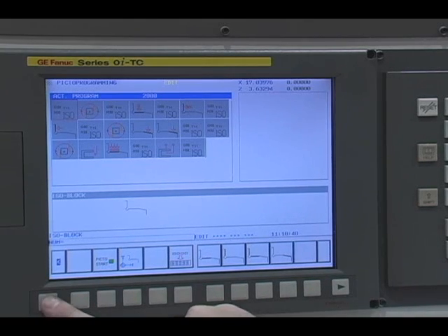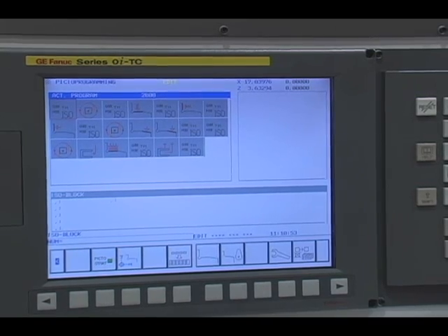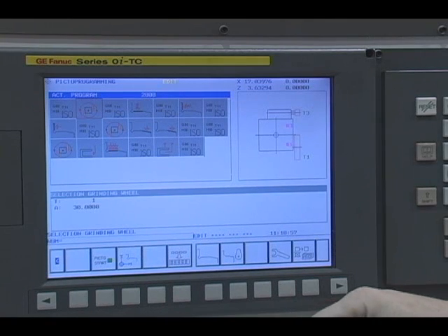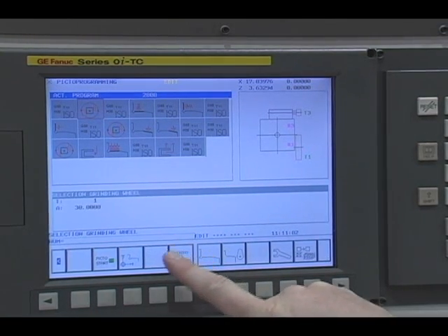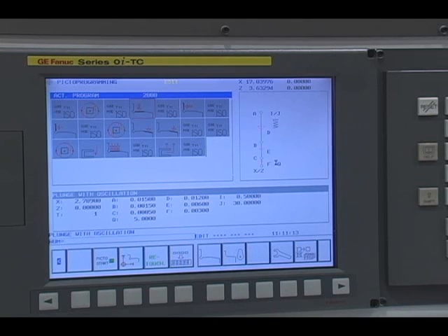So as far as our part print, or the part that we just selected, as I cursor through here, you can see on the information block the information that's in the pictogram. So my wheel selection, first operation, the grinding wheel was set up at 30 degrees. I give a command for the gauge to go in. We're going to monitor and gauge that first diameter being ground. And the cycle I selected was plunge with oscillations. You look at your part drawing and you nominally dimension.